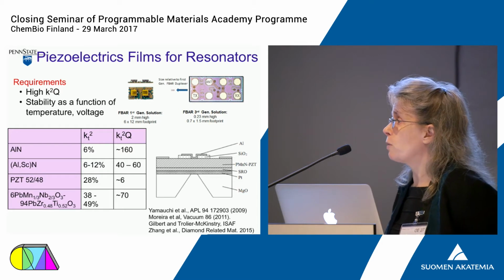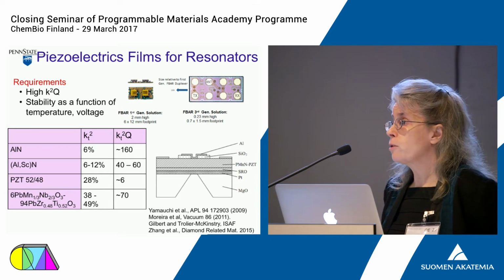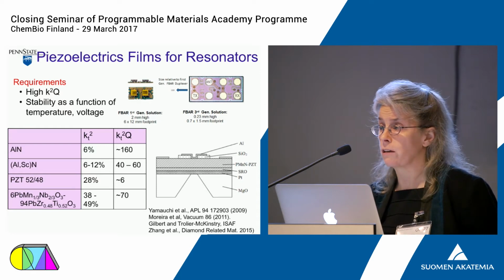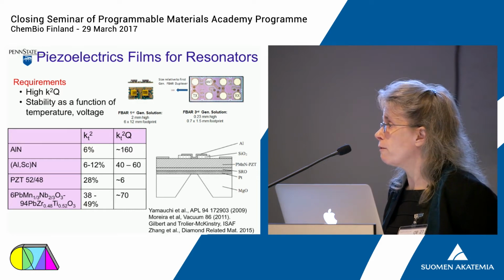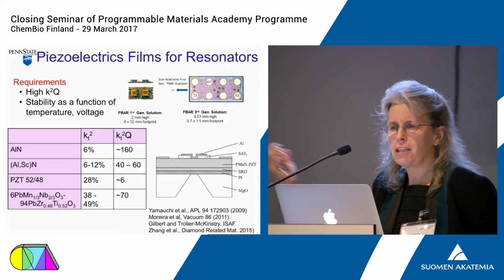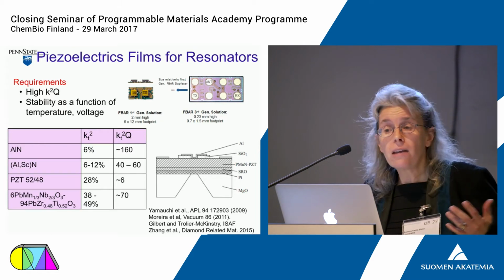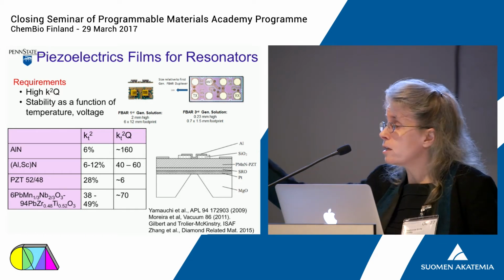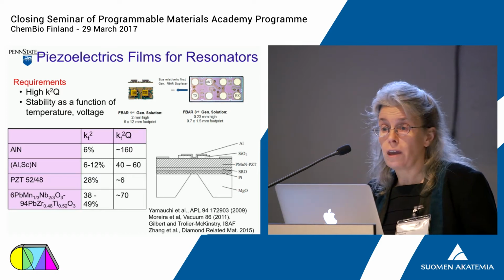All of you are carrying around piezoelectric thin films for microelectromechanical systems. They are the frequency filters that are used in your cell phones, that are used to distinguish between the transmit and receive portions of the circuit. I think most of you will appreciate that if you were to compare the cell phone of today to the cell phone of 10 years ago, which was a nice brick, quite heavy, didn't speak on as many frequency bands, one of the main reasons that those phones were literally larger is that they used a dielectric resonator that was roughly the size of my finger to do that frequency filtering.